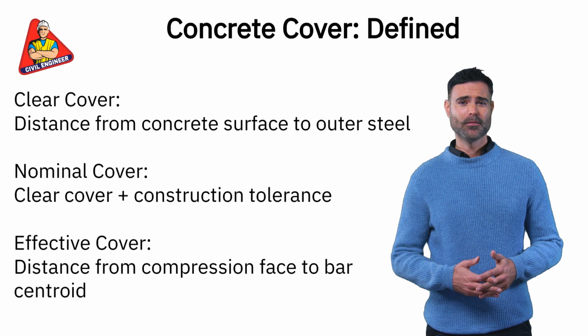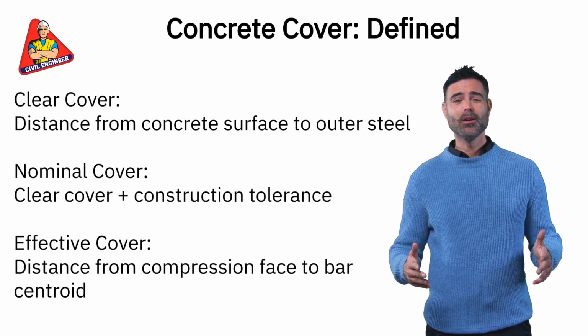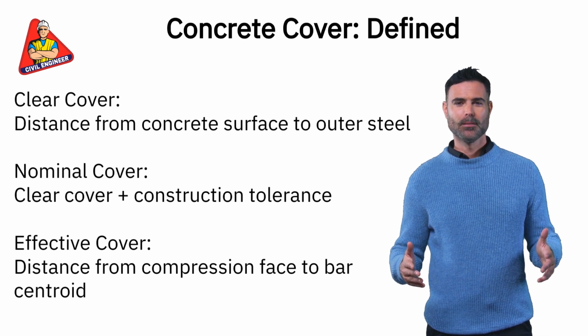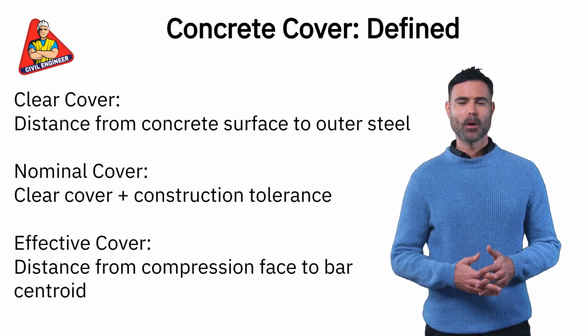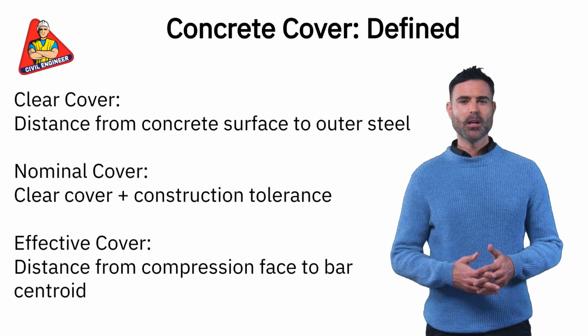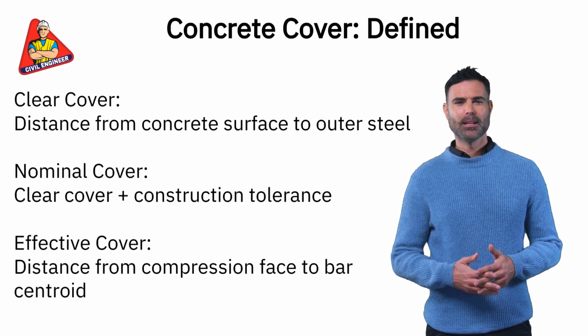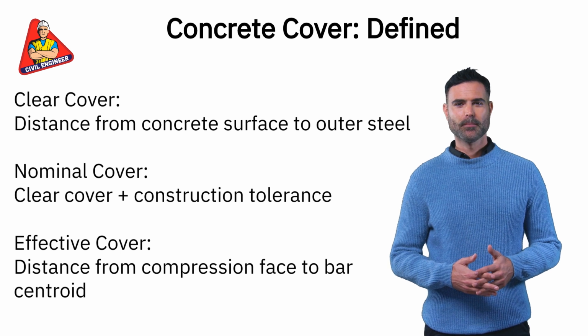3. Effective cover, critical for flexural design, is the distance from the extreme compression fiber to the centroid of tensile reinforcement. This dimension is used in moment capacity calculations. The correct interpretation of these terms is essential for both design and site execution.